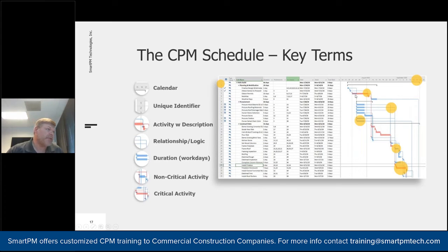You can see it will tell you even visibly what your critical path is. A lot of times I meet with people that never even turned on the little identifier of the critical path. And they're not necessarily always looking at total float, but you can see right here where it says 0 days of float, those activities are red. That means we have 0 days of delay room. And then there are activities that are blue. And this is in Microsoft Project. Primavera is similar, it's green and red over a calendar, but a series of activities with durations, with some sort of order imposed, and the program does the work. It tells you what things can happen, when the soonest something could happen is, and what sort of room for delay it has. And if it's red, that means it's got no room for delay.